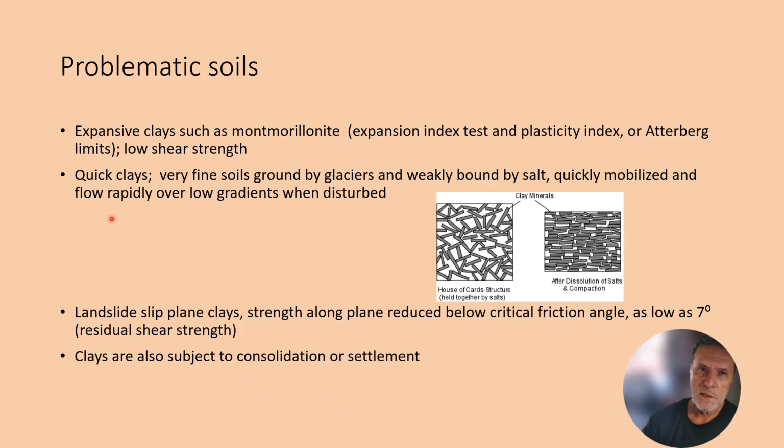Okay, now let's talk a little bit about problematic soils. This refers to a very unusual soil or unusual soils. You have expansive clays, including montmorillonite. When you add water, it'll swell. It's got low shear strength. If you put it in direct shear, it fails pretty easily.